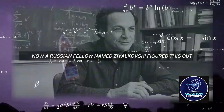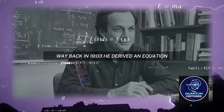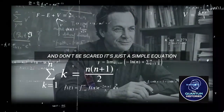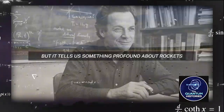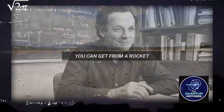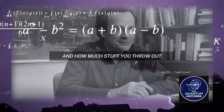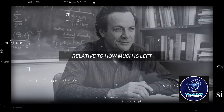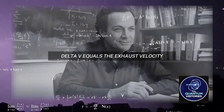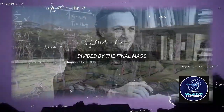Simple, right? Now, a Russian fellow named Tsiolkovsky figured this out way back in 1903. He derived an equation. And don't be scared, it's just a simple equation, but it tells us something profound about rockets. The equation says that the change in velocity you can get from a rocket depends on two things: how fast you throw the stuff out the back, and how much stuff you throw out relative to how much is left. That's it. Let me write it out for you. Delta V equals the exhaust velocity times the natural logarithm of the initial mass divided by the final mass.